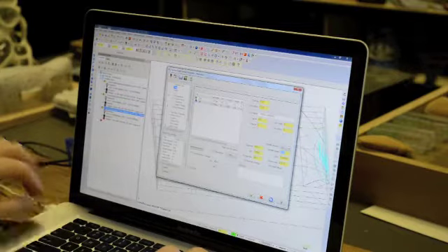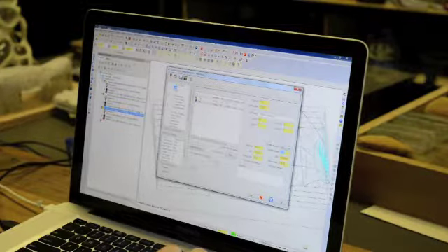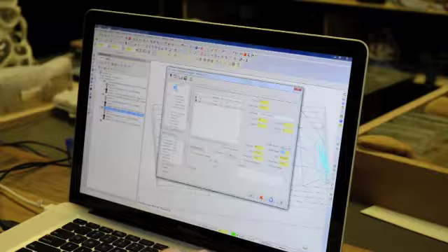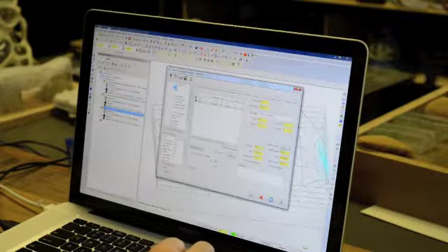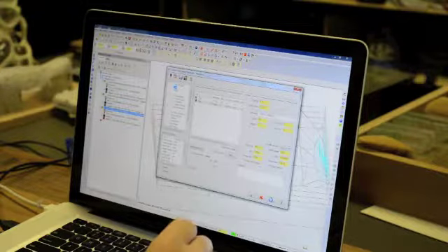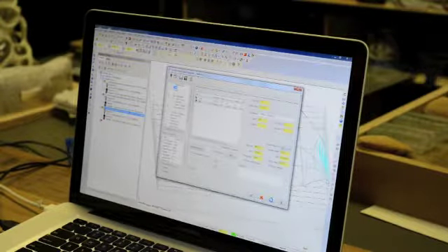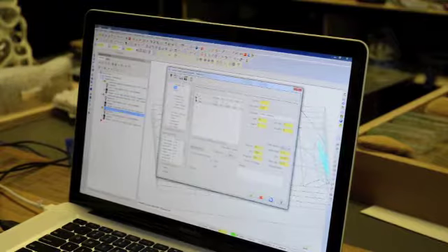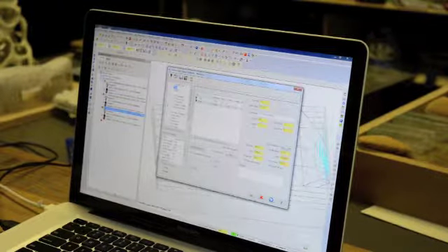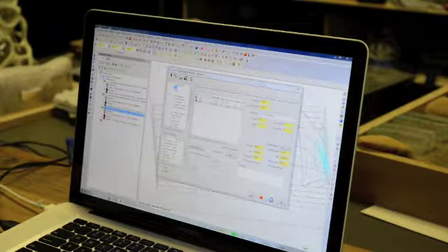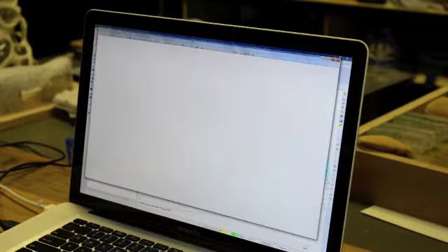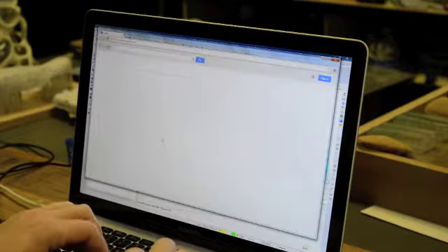And then for our spindle speed, this is where we need that chip load chart again. And I guess one question maybe, why do we always use this feed rate of 500? And that's kind of an issue of how much time it's going to take us to mill this, so we always just max that out. And let's get the chip load chart open. And this is also a Vortex tool, so we'll use their published values again.